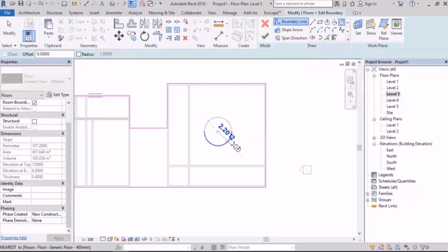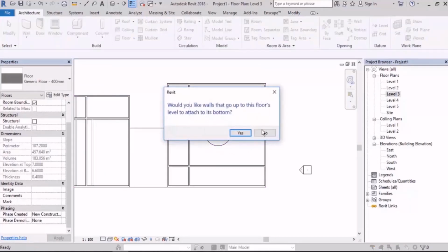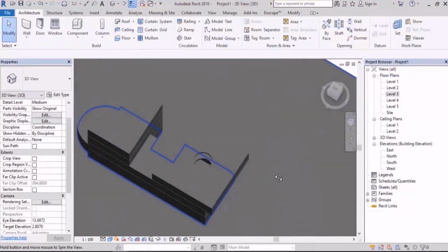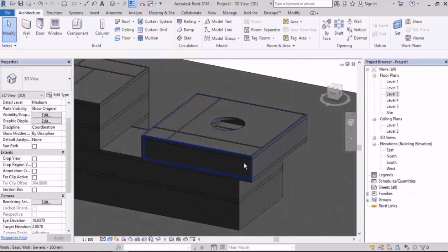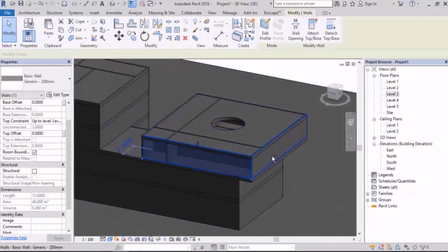Alright, the last thing that I'm going to tell you in this episode is creating the shelter. To design the shelter, we have two methods, and one of them is not useful at all. I just tell you to know it, to be aware of it. One way is that you make a top offset for the wall. For example, we want to create a shelter here. I select this and this one, and then I go to top offset and, for example, make it 1.10.